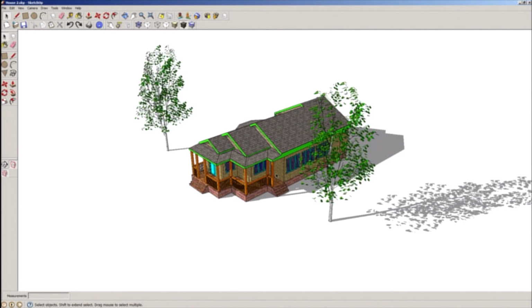The way I generally approach this is I have two categories of geometry that I look for to remove. The first category is things that are too complex. Either they're too high poly, or they have too many materials, or a combination of both. And normally this is high poly components, like these trees you see here, or sometimes people just put very, very detailed, complicated parts of the model in.